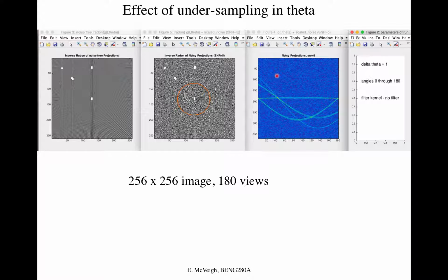We may also try a sliding window approach wherein we find the variance within that sliding window. If the variance is higher, it means there's actually a signal in it. Yep. And otherwise, it's noise and it can be filtered. That's exactly right. If I have my box and I'm sliding along like this, and I get the same statistics over and over again as I'm sliding, I just do the average.